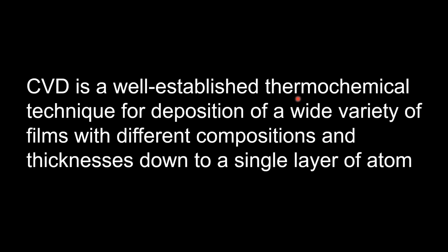So this means the chemical reaction on the surface of the substrate will occur due to heat. So CVD is a thermochemical technique, and with it we deposit a wide range of thin films.